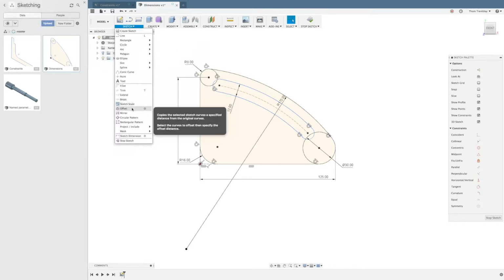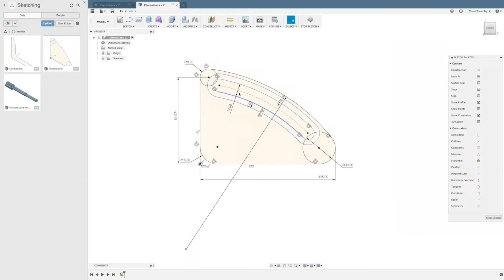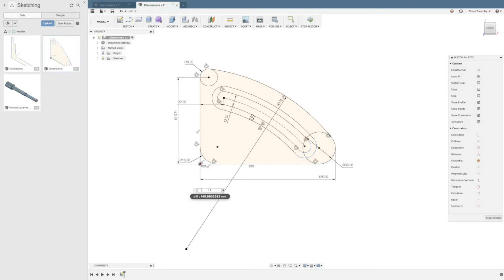geometry. Also, if you use the offset tool, drag out your offset value, and it will automatically place a dimension using that same approach that I used for this 12mm dimension. Okay? So one other thing I want to do is use a couple of more dimensions to locate this sketch. Let's build that off of the edge here, maybe apply a radius to the center itself.